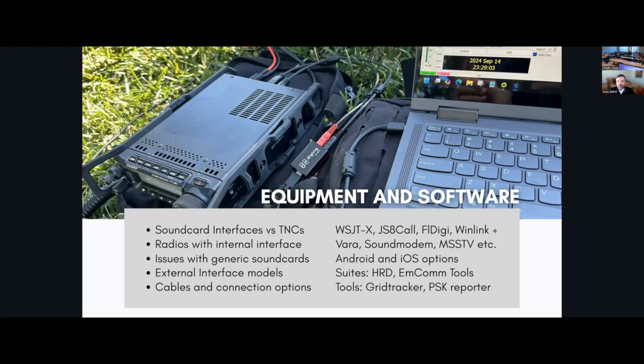So if you were to run APRS, you have a choice to use TNC or the sound card. That's another option. But TNC is a one trick pony. It makes it convenient, but it does it internally, and it can only do one mode. So if you were to try FT8, or if you were to try to do slow scan TV, the TNC will not work. So this device that incorporates encoding is a close equivalent to a dial-up modem, because we would feed data into the dial-up modem and the audio will come out. Another alternative, which Digirigs are, is the sound card.